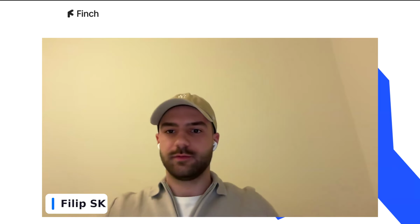A little bit about the key figures. Can you include the balconies in the gross area? Yeah, so this just depends on how you set up your project. You can include balconies in the mass and then you can mark them as balconies, and then for every space that you create, you can control if it's included in GFA, GIA, NIA, UFA, all of that. So you have that control for sure.